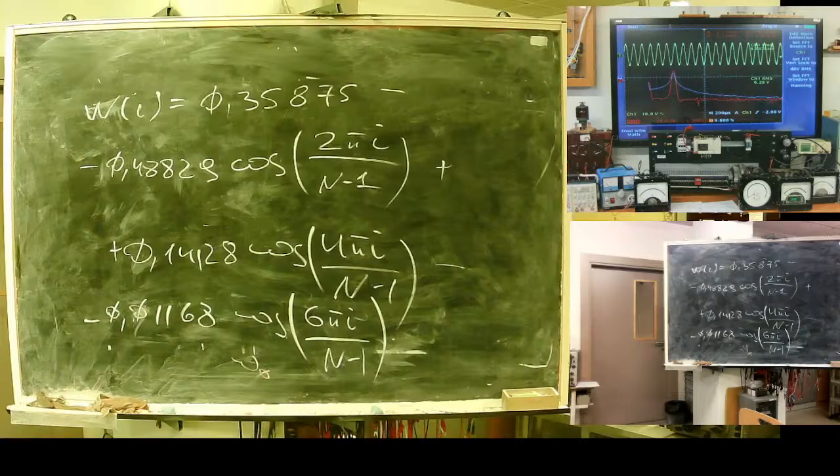Hann. Again, improvement. Hann gives 31 decibels, and the spread is 1.5 times wider than rectangular.